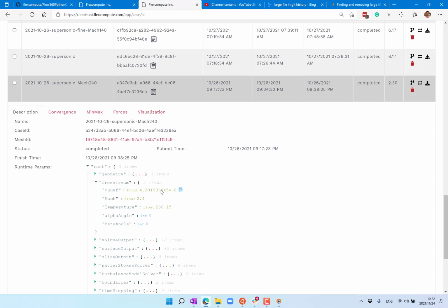Okay, so one solver unit in terms of speed gives you actually the free stream speed of sound. The solver unit for density is the free stream air density. Okay, with these two solver units, I think you can actually back out the solver unit of everything else.